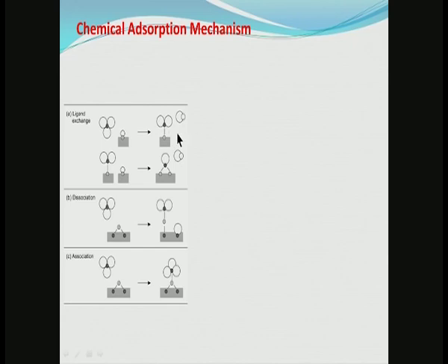When the next precursor comes in, that is, you have one layer and the next precursor comes in, what can happen is ligand exchange. So, a part of the molecule that comes in exchanges a part of the molecule that is already adsorbed, and that is called ligand exchange, and therefore what you are left with is this kind of a layer, as in the case of aluminum oxide.